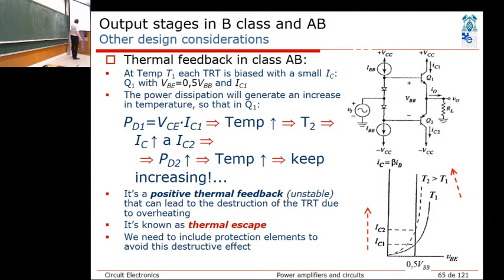Basically, I would put a thermal fuse next to the amplifier circuit, so the thermal fuse blows off before the thermal destruction would happen. That's why those thermal fuses are there. You put one there and cut the power from the circuit.